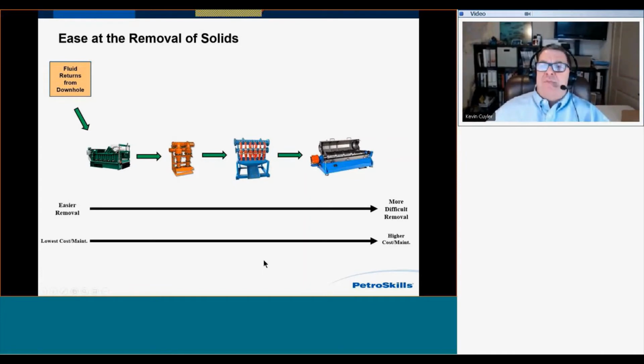Many people often ask me at this point, well, this is great for water-based, Kevin, but what about when we have oil-based mud? Very good question. Remember that we will not run a desander and a desilter, but we will run what we call our dual centrifuges or barite recovery centrifuges. And we run those to help keep the barite in the system. We separate out the low-gravity solids and our slurry, our expensive base oil. We recover that, and we remove the low-gravity bad solids, returning the base fluid, the base slurries, back to our system. So a very, very similar type of operation.